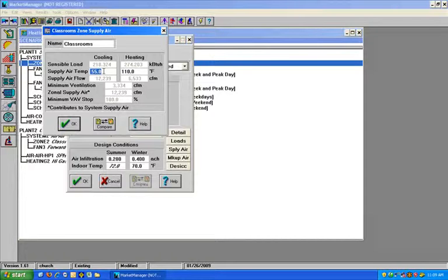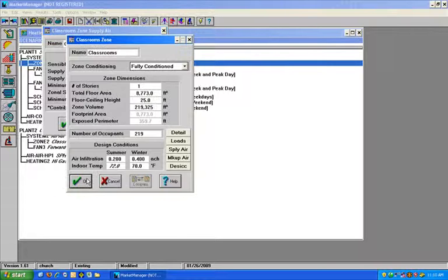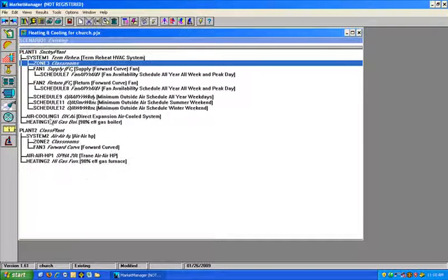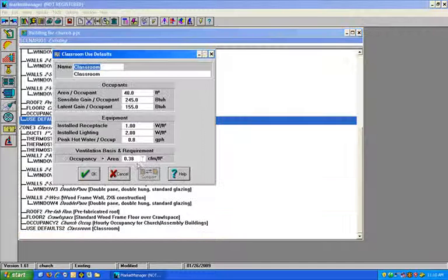So I have Q, I have my 1.08, I have my delta T. The only thing left is CFM, and that's what we're calculating in this form: what is the zonal CFM requirement. Well, for cooling, it's that, 12,000 and something, and for heating, it's 6,500 and something. And then it will also look at your minimum ventilation. Now, the minimum ventilation is actually calculated here, but there are some user defaults which we haven't been looking at yet, but this will help us determine our ventilation.